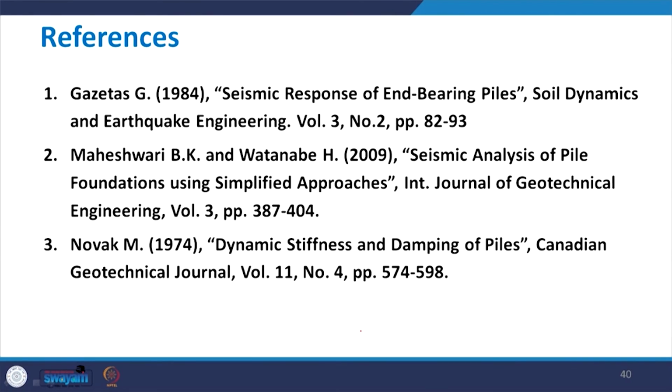R0 is d by 2, the radius of the pile, so nothing needs to be mentioned there. So, this was the Gazetas hypothesis, and Gazetas presented graphs or charts for kinematic interaction factors and kinematic amplification factors. The rest of the things you can find in the first reference, listed by Gazetas, which is published in Soil Dynamics and Earthquake Engineering.